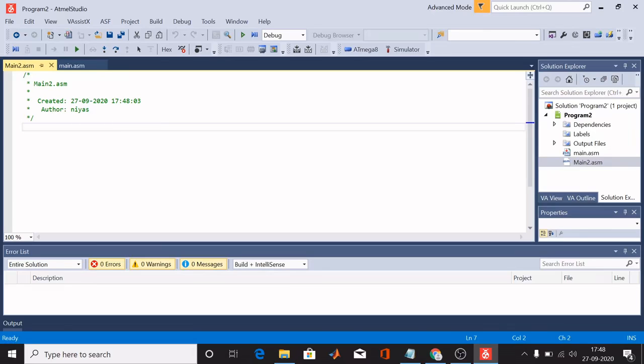One way to overcome that problem is to give the values from the ports, or to define them in a lookup table. Here we are going to define the inputs in a lookup table, and if you want to change the input, we'll rewrite it in the memory space where the lookup table has been created.